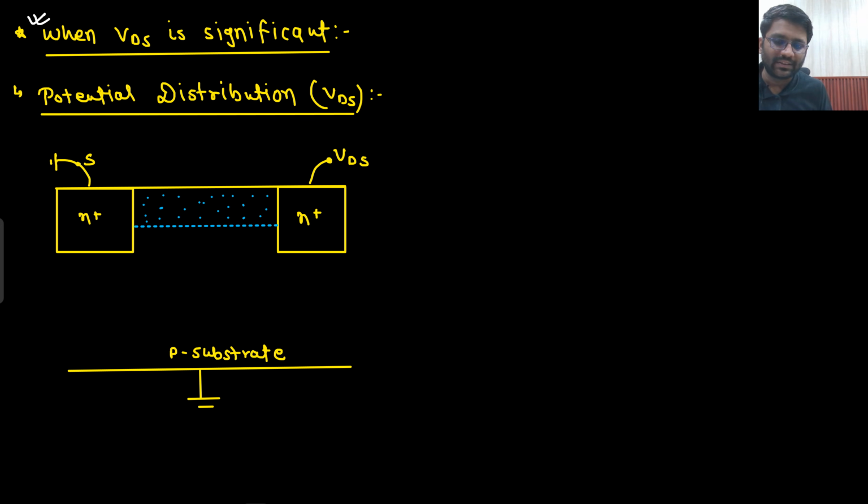So, basically this inversion layer has been formed. What does that mean? That means we have already applied gate to source voltage to be greater than VT. Like this is our gate. So, we have already applied VGS greater than VT. This condition we have already done. Now, VGS is fixed. We need to see the variation with respect to VDS.